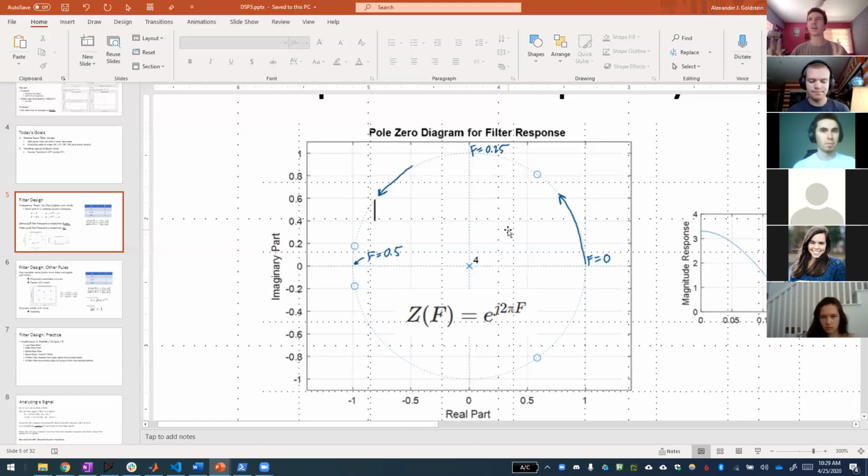And remember, it's not exactly multiplying, but for this, it doesn't hurt to think of it like that. With convolution, you're basically taking whatever point you're at and multiplying it by the zero and then dividing it by the pole. So if you have no poles or zeros, it's just going to be 1/1, and so it's just unity gain across the entire frequency spectrum.